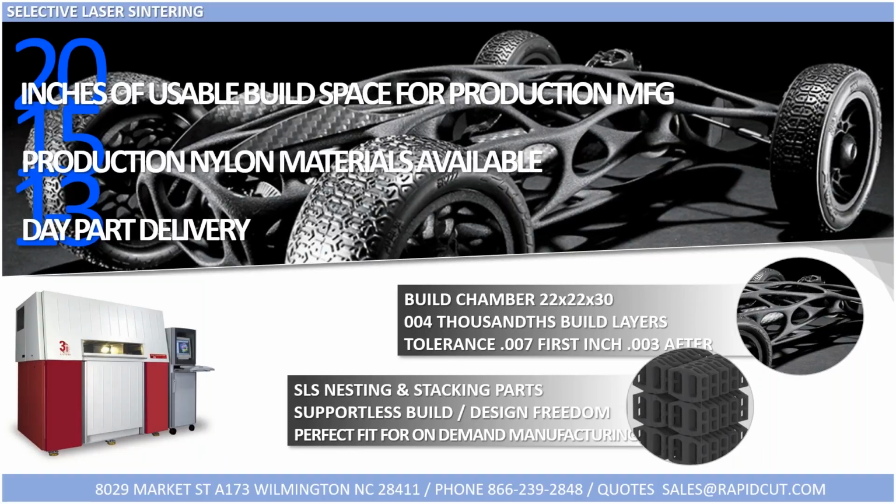Up next is selective laser sintering. Now this is the beginning of what I call the proto-functional style parts. You see SLS utilized heavily in additive manufacturing programs in everything from aerospace to common consumer products. The biggest chamber we currently have is 22 by 22 by 30. We're going to be building again in 4,000ths build layers, and your tolerances are going to be consistent here with the other processes: 7,000ths for your first inch, 3,000ths thereafter.